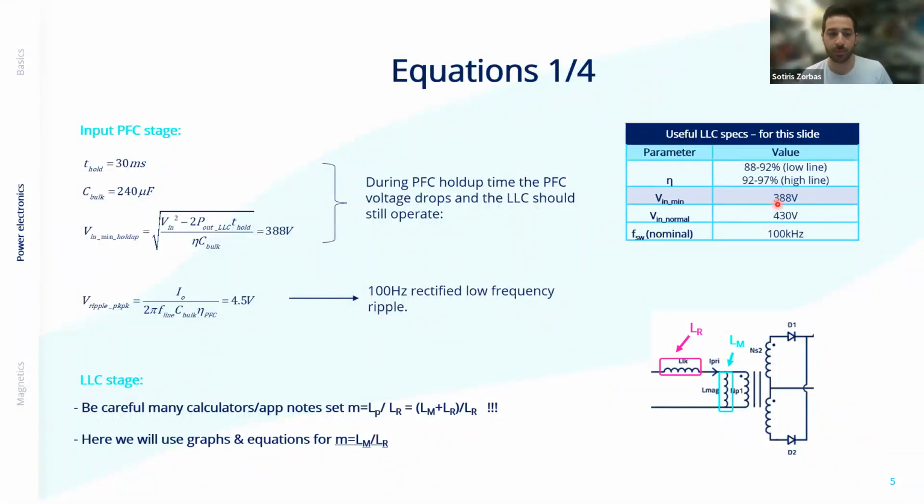So where is the problem? The problem is, for example, in a power supply, when there is a dropout, it's not called dropout, my English, it's a brownout condition. So usually we specify a hold up time of 20 milliseconds, something like this, 20, 30 milliseconds.